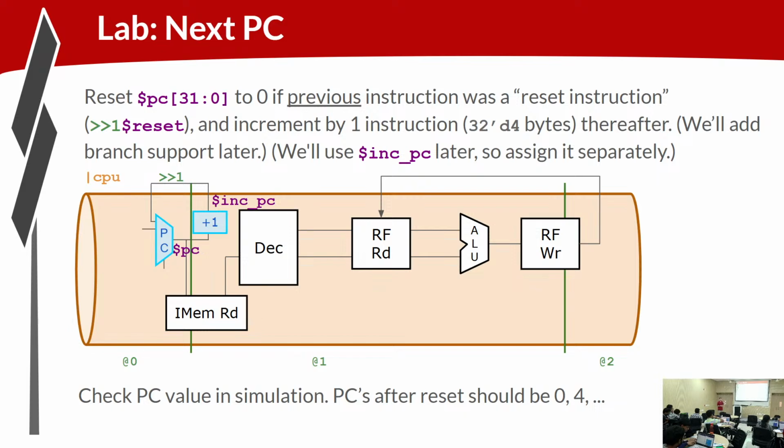TL-Verilog, to enable the other forms of abstraction that are valuable for hardware, uses this single assignment model. So your assignment of the PC here is a complete assignment of the PC. We don't have the sequential semantics where we can assign it and then, oops, let's reassign it to something else. It's more declarative of the hardware. And that's why, for things like muxes, we use the ternary expression. It's all in one expression to completely express all the different cases that we might have.